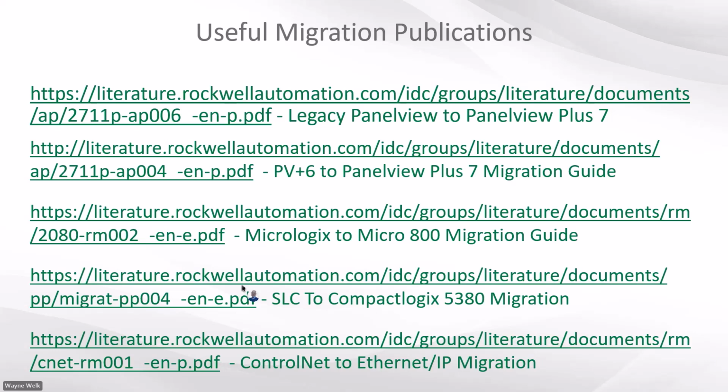There is a conversion code utility tool. In fact, I will say Rockwell on their Studio 5000, RSLogix 500, MicroLogix, we do have conversion utilities. The only thing is, because a lot of times the newer programs are completely different, we can only migrate the programs 60, 70, 80% of the way, depending on how the code was written. So this is not a magic bullet conversion. It's not going to make everything great, but it will do a lot of the low end work for you.